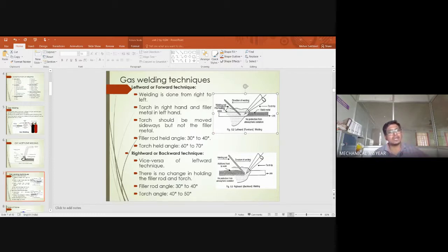The only difference is here we'll be having a reel feed unit which continuously feeds your consumable electrode to the electrode holder. So it is quite similar in construction. We have a power supply, the positive terminal is connected to your electrode holder, and the negative terminal is connected to your workpiece. And you can see here also the supply of gas is present from the shielding gas cylinder. You can see the pressure regulator and pressure gauge available, and the gas is sent to this particular nozzle area where we have two openings. One is for your electrode and another is for your shielding gas to come.